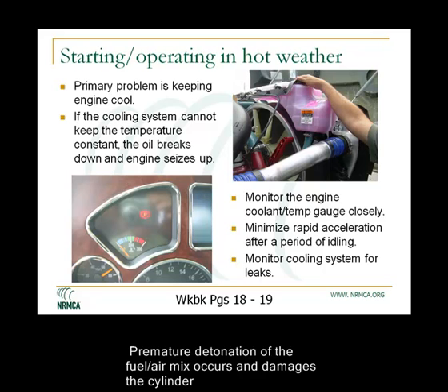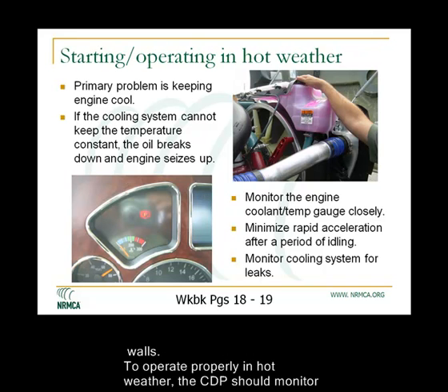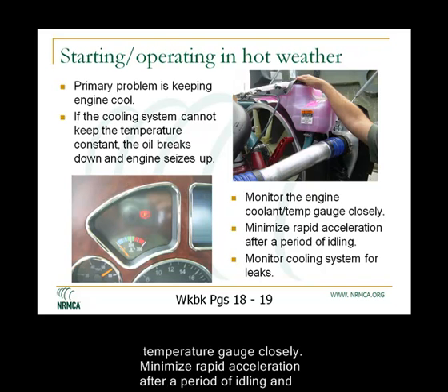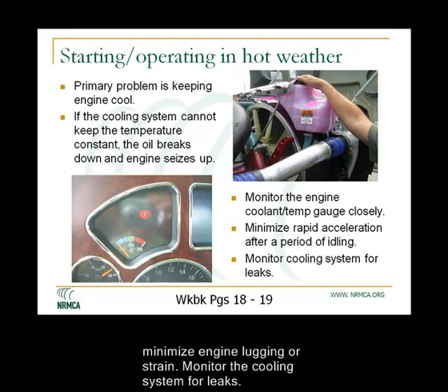To properly operate in hot weather, the CDP should monitor the engine coolant temperature gauge closely. Minimize rapid acceleration after a period of idling and minimize engine lugging or strain. Monitor the cooling system for leaks.